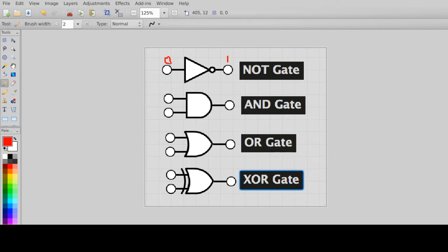Now, at this point, you're saying, well, how is that a machine? How do you feed a 0 to a machine? Well, it depends on what you're making the NOT gate out of, but our NOT gates are made out of electronic components, out of transistors. You can make them out of lots of different things, which we'll talk about in a minute. But that 0 is like low voltage, so you're actually feeding a voltage in here.